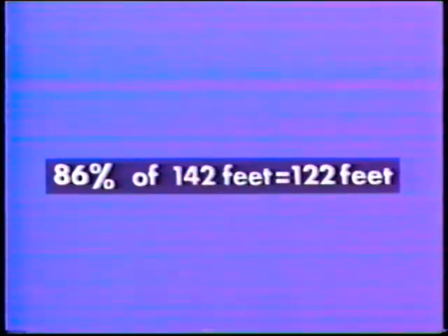To adapt that information for three-phase circuitry, we have to take 86.7% of that number. We said we'd round it off, so we will. 86% of 142 feet is 122 feet. So for three-phase circuitry, a size 12 AWG can span a distance of 122 feet with a voltage drop of 2%.